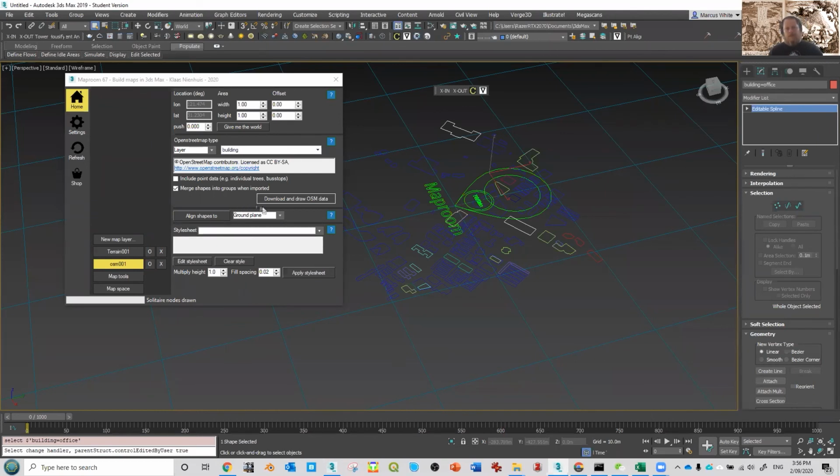But there's style sheets that you can apply. And if you were representing stuff that isn't building, you could bring in a GIS data set of type 2 diabetes density across Australia or something like that, based on statistical areas, for example. And you might then set up your own little custom sheet that uses the number of occurrences as height. In our case, we'll just stick to the standard kind of OSM style sheet. You can exaggerate the Z, but I don't want to do that. I'll just click on apply.